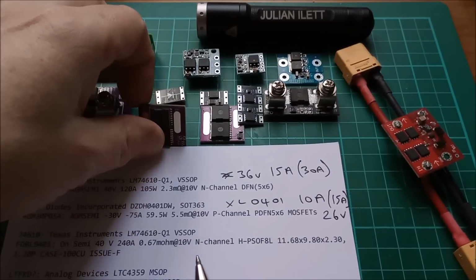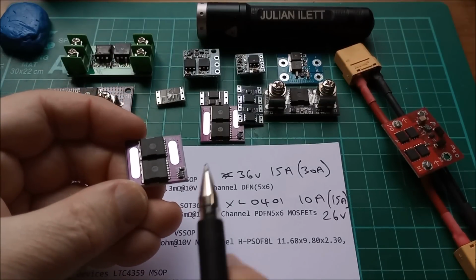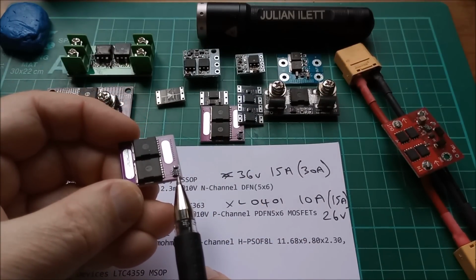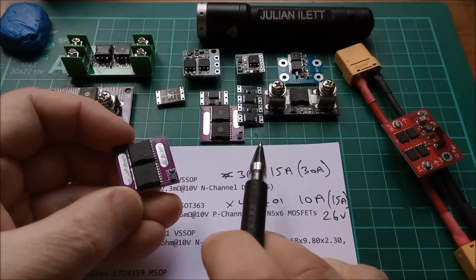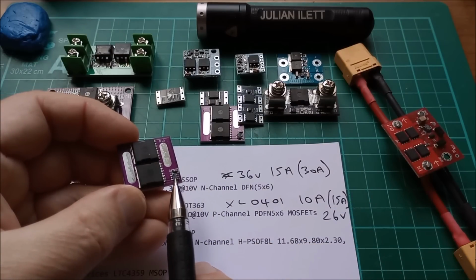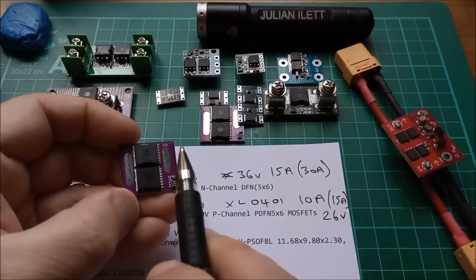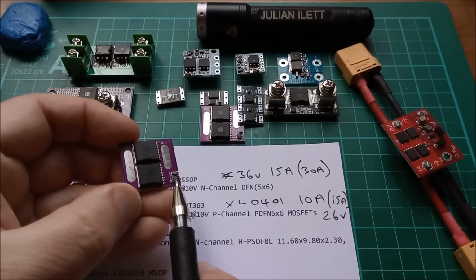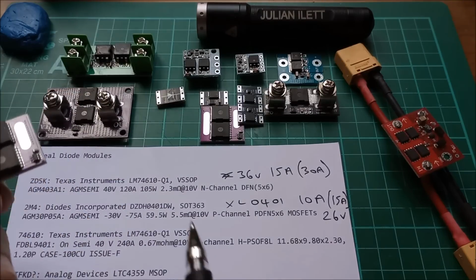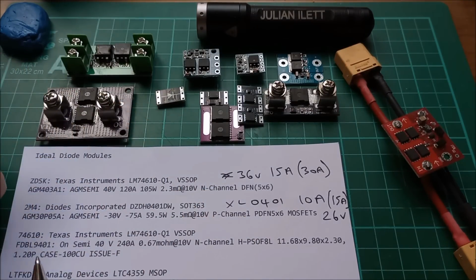That's this one where the chip is marked 74610. Now these two that I've received subsequently are both scraped, but the one that I fitted to that little voltage controlled relay, which is now in the shed, actually has 74610 written on it, so I know that that's the controller chip for this module. All it is, is a controller chip and a capacitor and a couple of N channel, or on some of these modules actually you just get one N channel MOSFET. So the details are here.